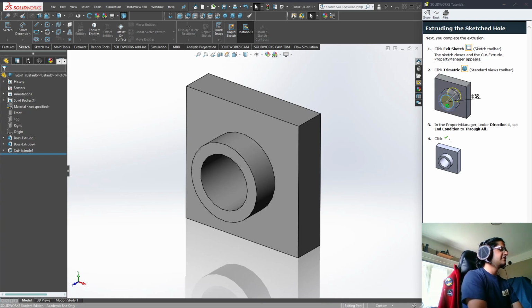Oh. That's 50 meters. Oh, whoops. So I have to. Okay. Yeah, if you look at the very left, it says 50 and just add another M there. There you go. All right, check mark on the top left. Confirm your action, and then on the very top you see exit sketch.